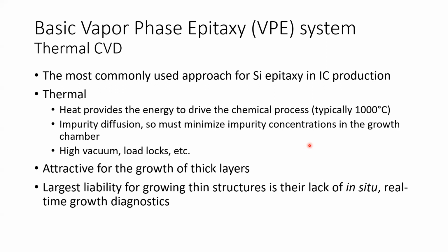And typically it's done in high vacuum, and we can also use load locks, or a small moving box, to transport the wafer into the larger chamber. It is very attractive for the growth of thick layers. The biggest problem for VPE is the lack of in situ real-time growth diagnostics.